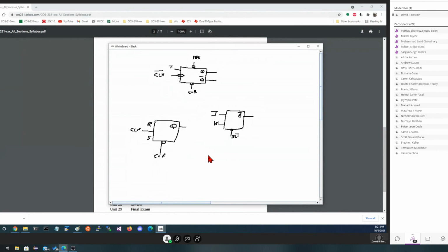Patricia, what do you think this is? A level clock RS latch. Right, it's an RS latch with level clocking, and it has a clear, okay, because clear is one of the asynchronous, so asynchronous clear. You might also note to somebody that it does not have an inverted output, right? It only has Q, it doesn't have not Q. So you can be very descriptive in filling in all the words just from this simple picture. If we needed to plug in the not Q, we can't do it here without putting an inverter.